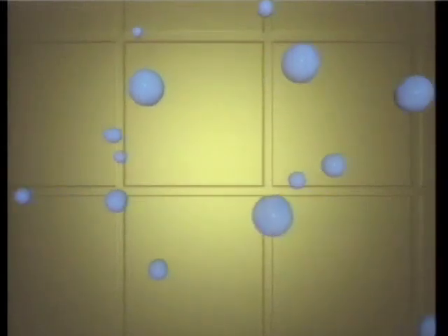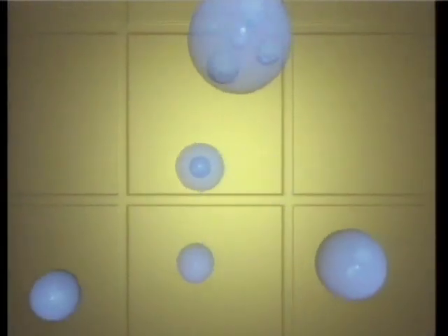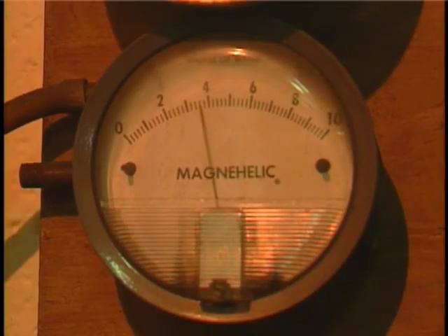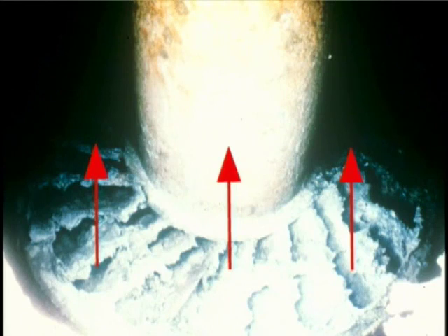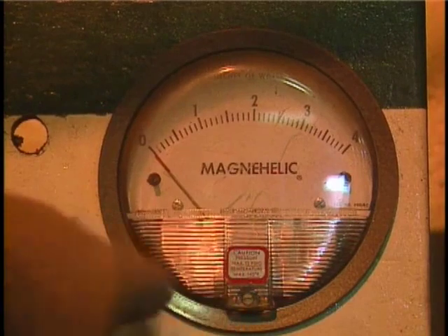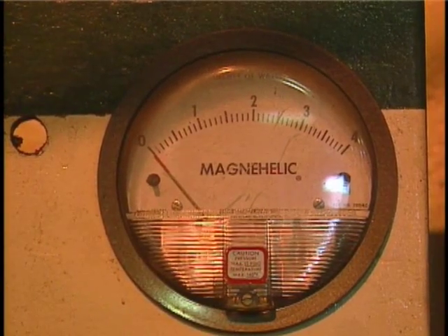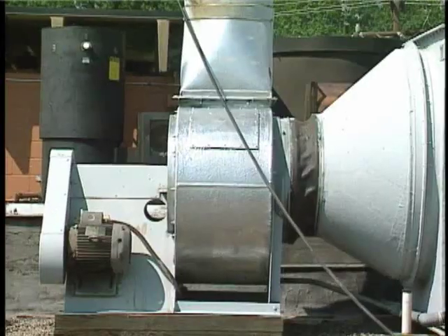For mist eliminators that are used to remove the relatively large droplets created in the scrubber, the increased pressure drop usually results from a buildup of material on the mist eliminator surfaces, narrowing the openings for the gas to flow through. The resulting higher gas velocities can drag the collected liquid through the mist eliminator and back into the outlet gas stream, reducing collection efficiency. A decrease in the pressure drop across the mist eliminator may indicate structural failure.